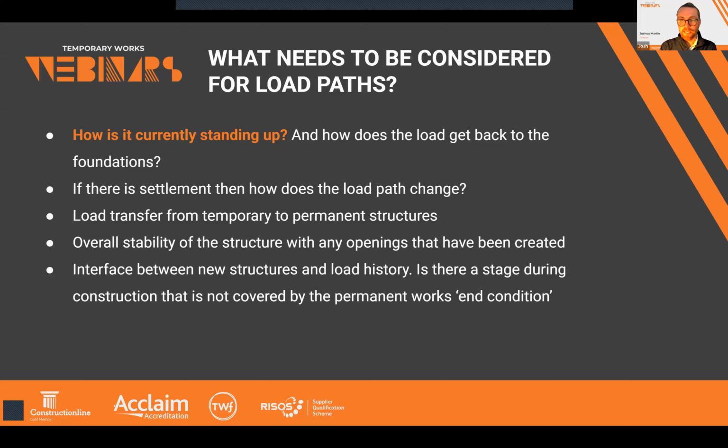Is there a stage during construction that is not covered by the permanent works end condition? By this end condition, I mean that if you have a structure that is being conventionally constructed from the bottom up, with stability mechanisms being constructed with the structure, then the worst case stability case will be when the whole thing is completed. So therefore, by default, all the previous stages are acceptable. However, if the structure is being constructed in a slightly different manner, then this needs to be considered by a competent person to ensure that the structure remains stable during construction, i.e. we've got those stability mechanisms in place.